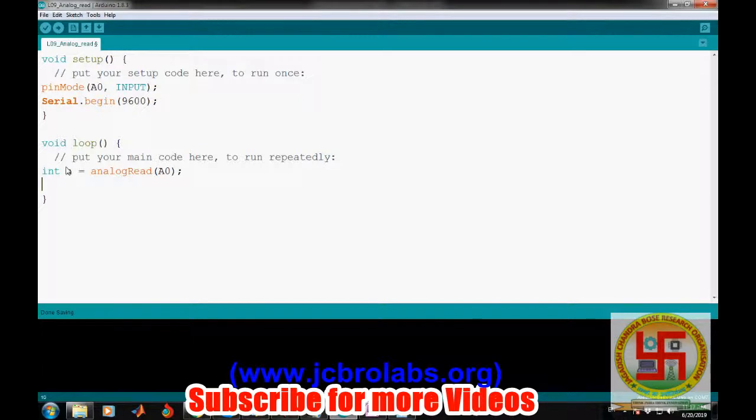Okay, so it is Serial.println, and we want to transmit a over there. If we don't provide a delay, then we won't be able to visualize the result. So to be on the safe side, let's provide a delay of 1 second or 2 seconds. Okay. Now let's compile it and upload it. So I hope it has been uploaded.